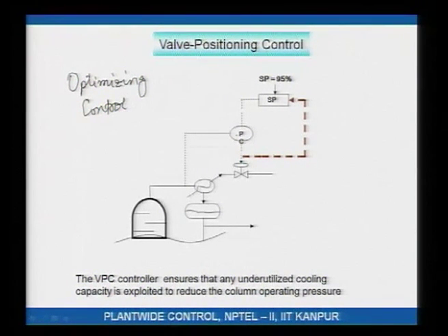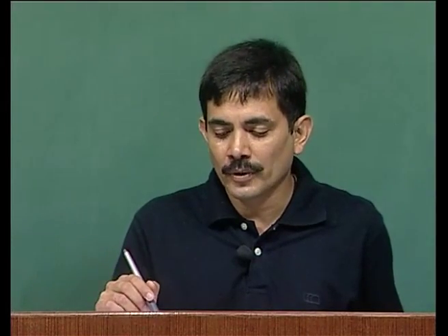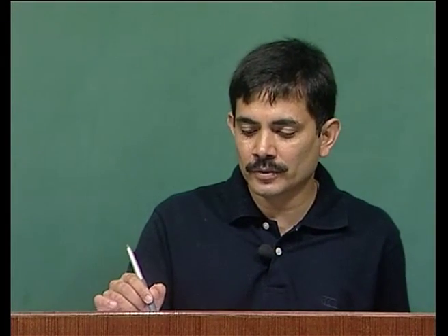Nights are colder, you are losing more heat, the column is losing more heat, and since the nights are cooler, the operating pressure of the column would be slightly lower, right. So, if you look at the diurnal cycle, you will see that the set point of this pressure follows the diurnal cycle. In the days, pressure increases, at nights pressure decreases.